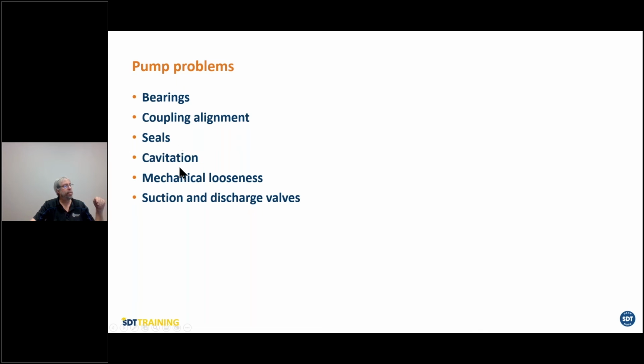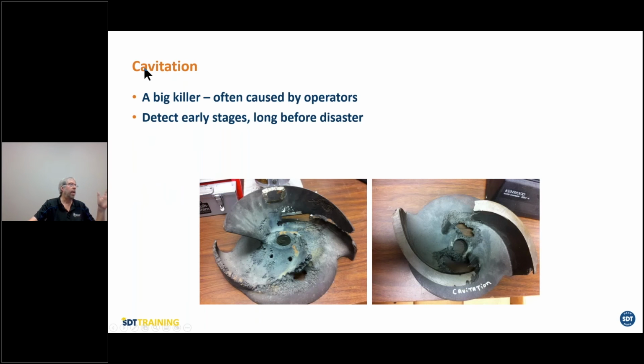You also look at seals, cavitation, mechanical looseness, and suction and discharge valves. Valves are very important in pumps because a lot of times they're neglected. Now, cavitation is a big killer of impellers. You can see how damaged these things are.